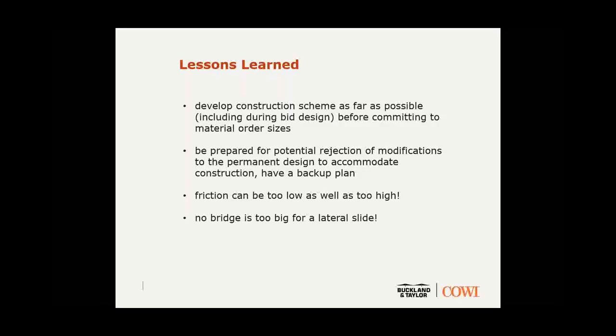Friction can be too low as well as too high. We had designed for frictions that we were normally used to. We got unexpectedly low frictions on this. The guys did a great job polishing up the girders, and that meant we had to scramble right at the end to make sure that wind wasn't an issue when we were sliding.